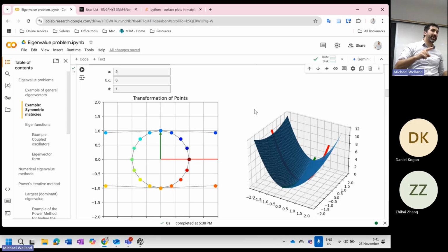And the solution is actually to break out your pressure, which is your spherical stress, as a separate variable. In doing so, you give it a little bit of extra wiggle room, and all of a sudden your material properties can work a whole lot better. Your models can work a whole lot better. So, but it's because of your eigenvalues.